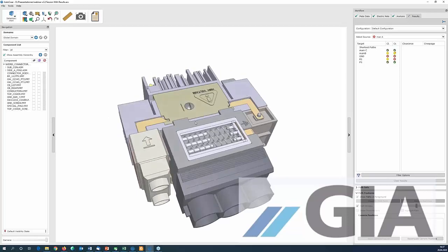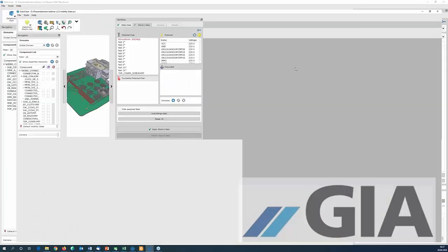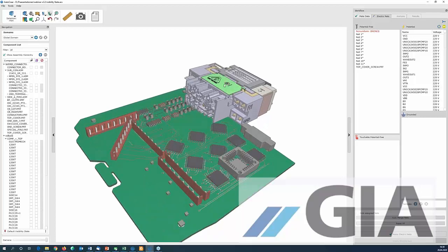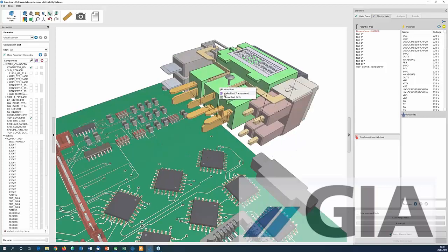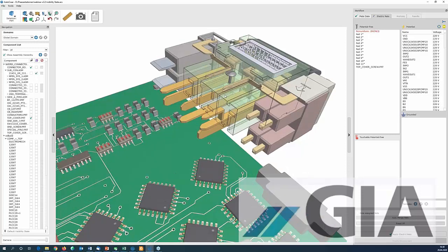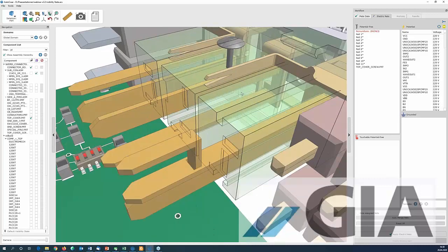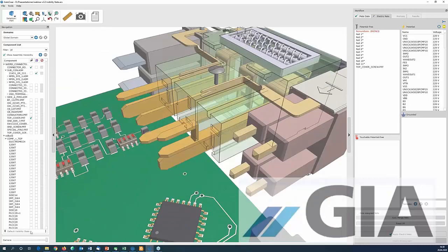Now if I change the visibility of certain parts, let's hide this one and this one, for example, make this transparent. For example, there's a nice view to the interior of certain parts, a view you might want to keep. First of all, I changed the default state by hiding, and this is indicated by the coloring of this pin.